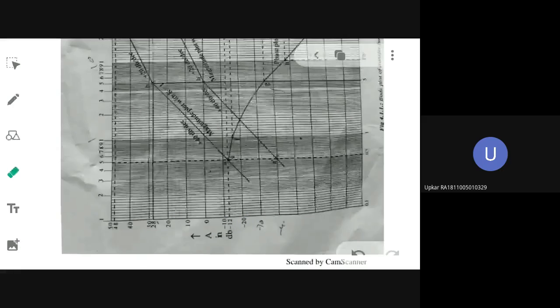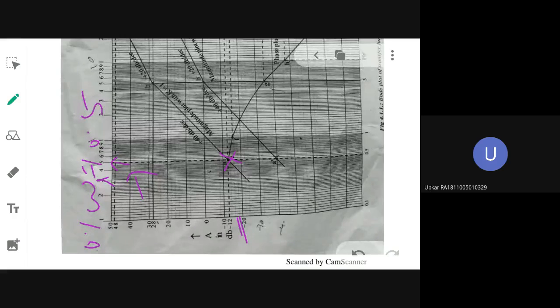Then omega equal to the least frequency, that is 0.5 radians per second, will come here. If this is 0.1, then 0.5 will be at this point. So this is point A, where the corresponding gain is what value? Minus 12. That you mark.